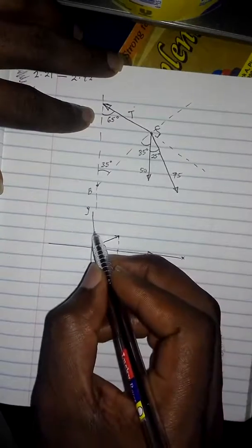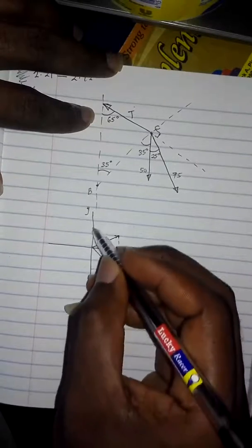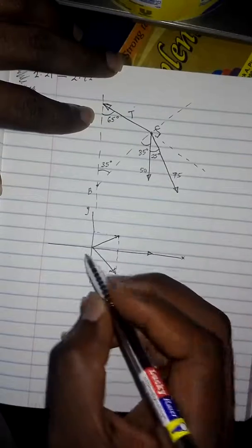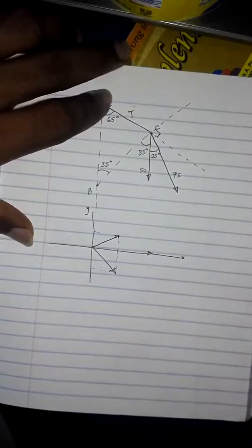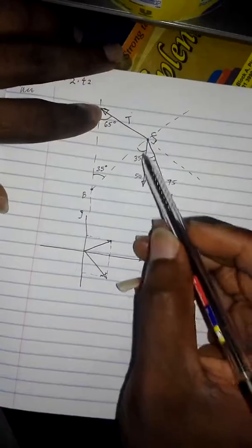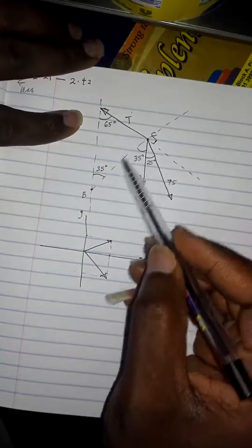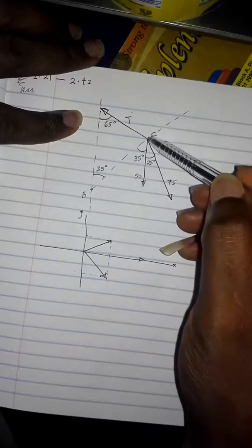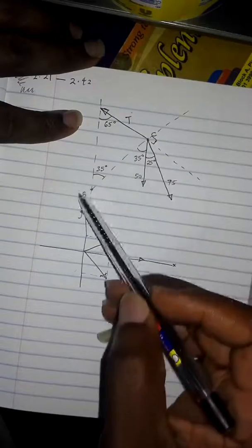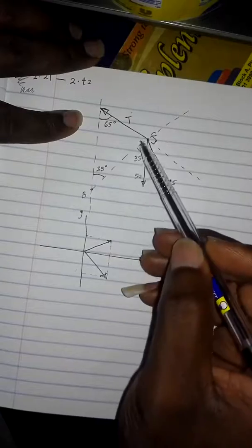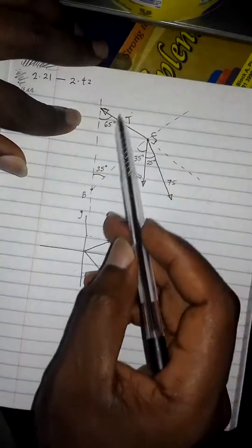If you now get their vertical components, their vertical components, when you add them, are going to become 0, because if it were not 0, their resultant would not have been in this direction. So that is the idea here. Because the resultant of this and this is known to be along this direction, the resultant of their components in the perpendicular direction is 0, because that is the only condition under which their resultant will be directed this way. So we can use that idea to get T, for instance.